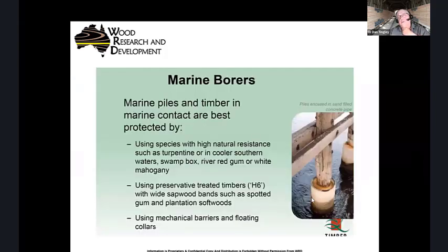Well, you can see this concrete block with sand. That keeps the marine borer, a crustacean that augers into our timber pile, then sieves organics from the water, and we don't like our piles being made into Swiss cheese. So we put this with sand there so the pile can shrink and expand.